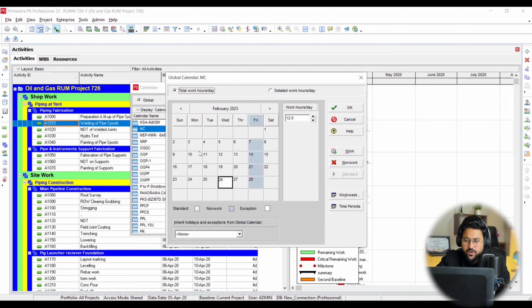Primavera P6 by default. So what you need to do, same like in UAE, 2nd December is their Independence Day, so you can make it like this one, non-work, so that Primavera P6 automatically calculates it as an off day. If you are working on this day, no need to do like that. So I'm going to close this one. This is the basic setting of Primavera P6.